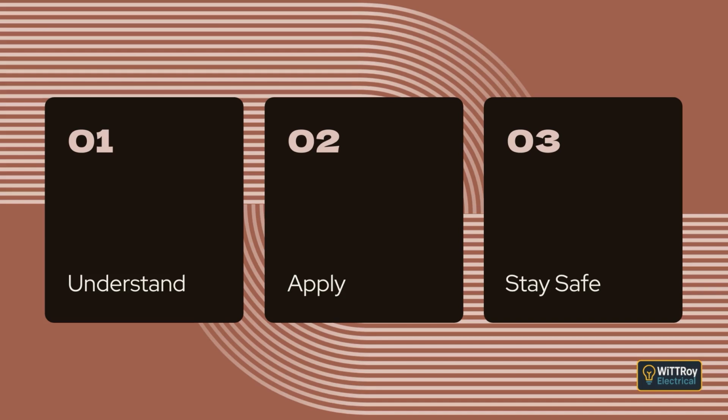Clause 2.9.2.2, Accessibility and emergency exit facilities. Switchboards must be placed so that access is not blocked by walls, fittings, or furniture. There must be enough space around all sides where work may be done. People must be able to leave the switchboard area quickly in an emergency.